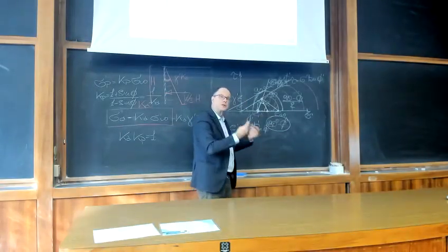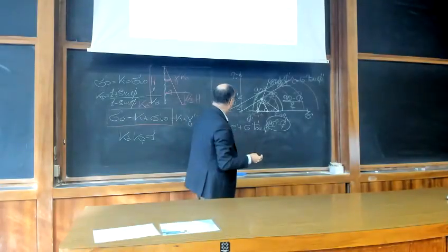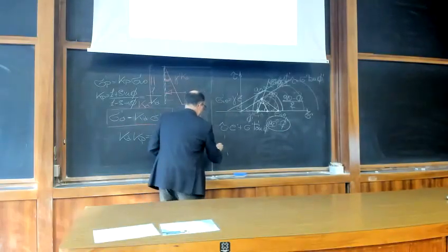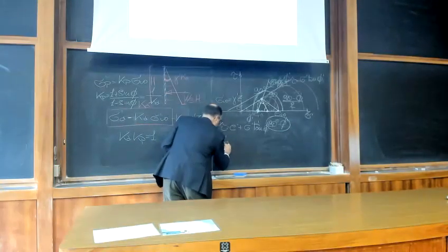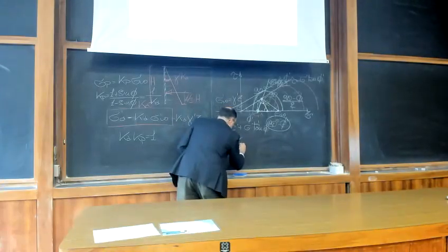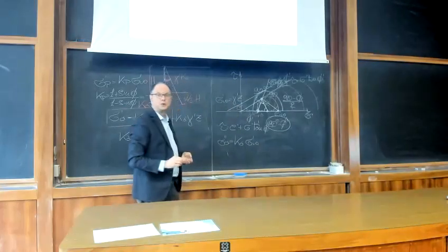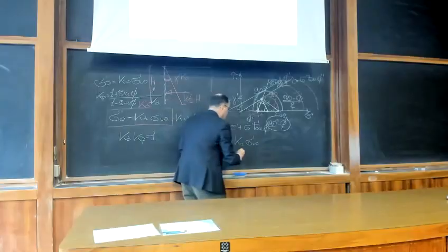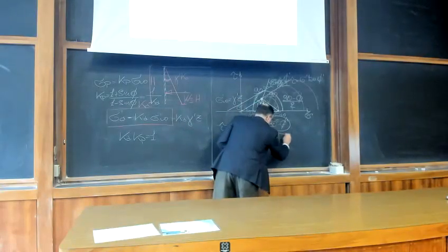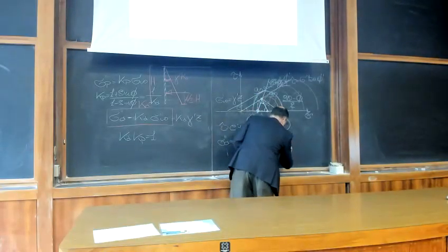So if you go through this, and I won't do it, so you have to believe me, your expression of sigma active will be Ka sigma prime v naught minus twice the cohesion multiplied by the square root of Ka.